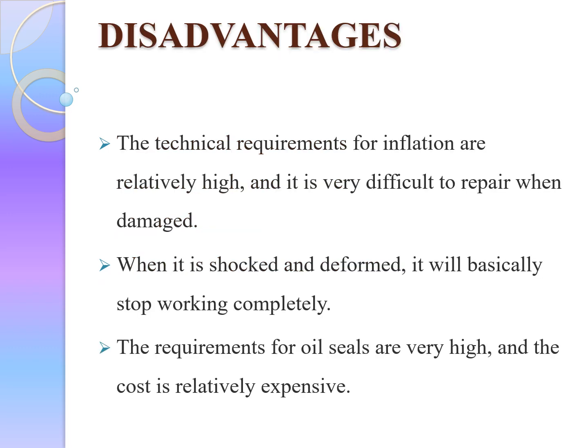And some of the disadvantages of nitro shock absorbers are: the technical requirements for inflation are relatively high, and it is very difficult to repair when damaged. When it is shocked and deformed, it will basically stop working completely. The requirements for oil seals are very high, and the cost is relatively expensive.